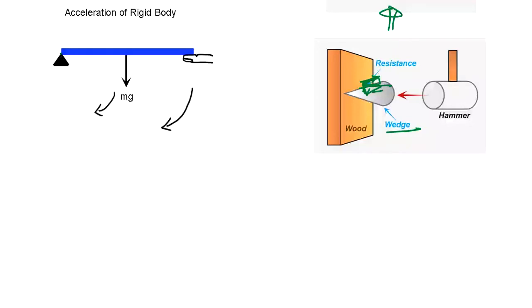Okay, let's work out some example here. Okay, this is the example. You're holding this bar mg, the length is L. You suddenly remove your finger. So what's happened to this rigid body? Okay, let's consider the rotational movement. It rotates around the center of gravity. So the gravity doesn't contribute to the rotational movement at all. It's hitting the center of gravity.